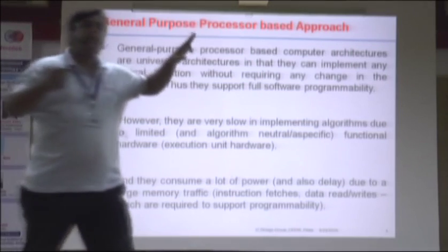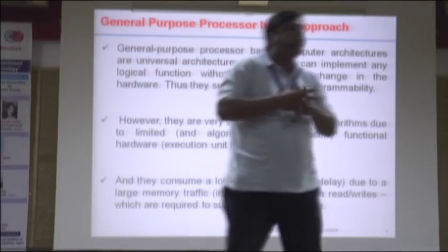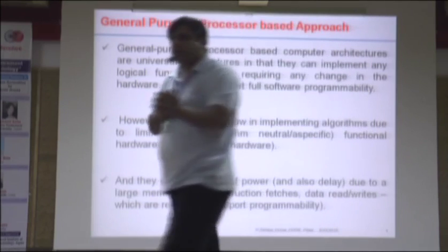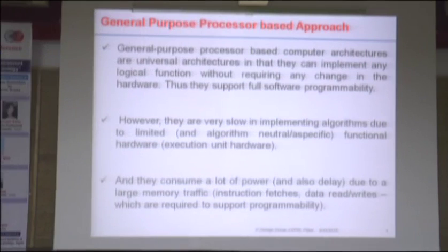So you require only 3 memory operations. And these memory operations, they are very slow in hardware. Okay. So they are the bottleneck. Okay. In determining the performance. So for example, if your sine or cosine or exponential function require 100 such instructions, okay, and one instruction will take 3 memory operations. So you require generally 300 memory operations, okay, to execute this operation.